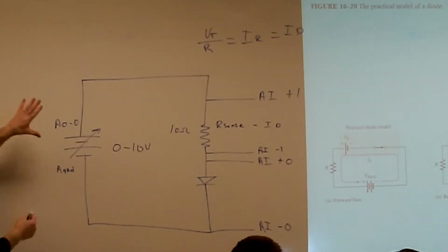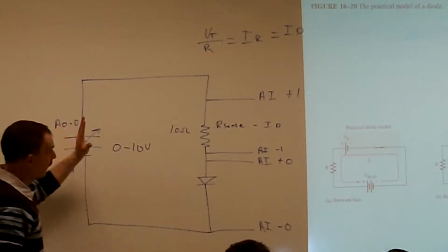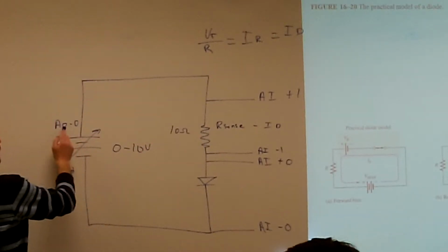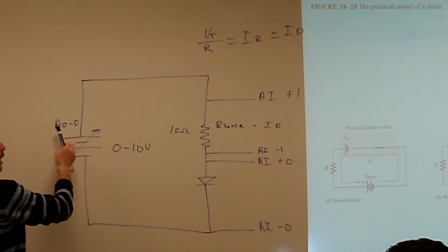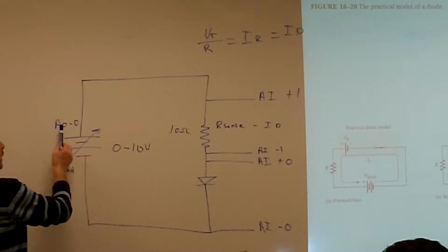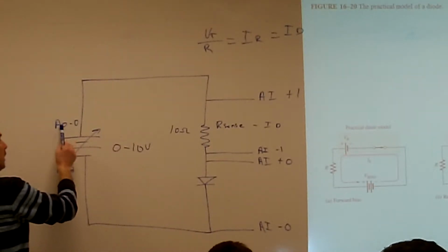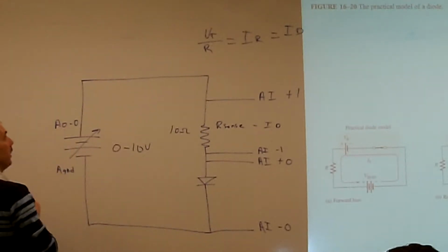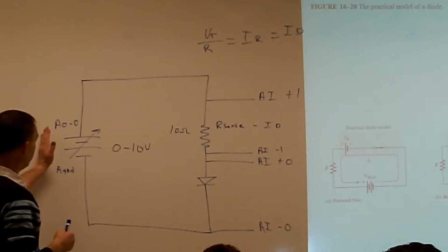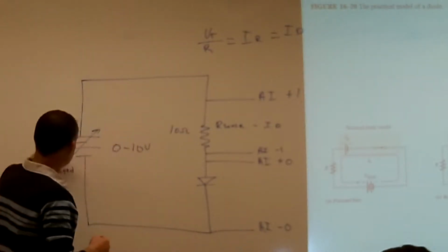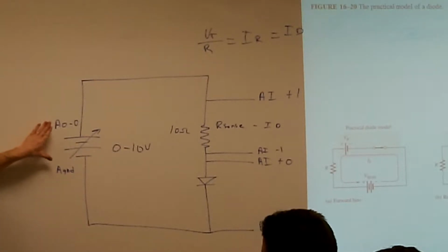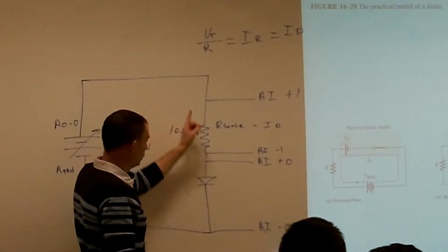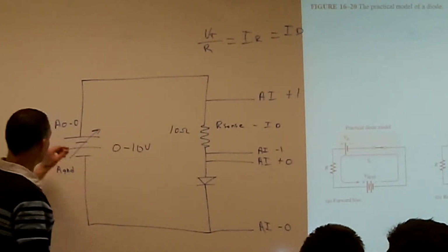There's always some confusion there, where we wanted to just bring that wire going into either our RC circuit or our RL circuit right to the analog output. If we call out the analog output, make sure that you're coming out of that op amp, the one that we wired up from day 1. So just start using that analog output. If we call for the analog output, either channel 0 or channel 1, make sure that you're coming out of the op amp. That gives us enough current to power up any of our circuits.